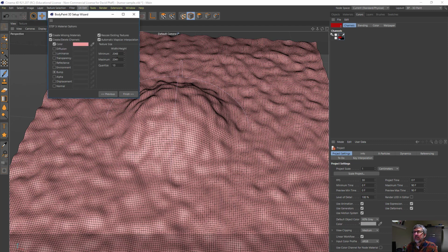So I'm going to click OK, and we're going to use a 2K texture, 2048 by 2048, which is a good medium texture dimension. These will be blank if this is the first time you've done this, so you need to know that this is powers of 2. You need to be 1024 or 2048 or 4096, but 2048 by 2048 is a good number.